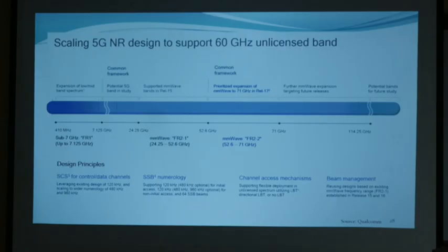These are the frequencies. In wireless communication, we need a frequency. The frequencies are very, very scarce resources. So you can see up to 7.125 gigahertz is called frequency range 1. That is a good frequency, it can travel far away. But this frequency range is already crowded with different services: the defense people, air traffic control, and police are using this kind of frequency. So the frequencies for cellular service are very, very limited. Okay, so these are the good frequencies.